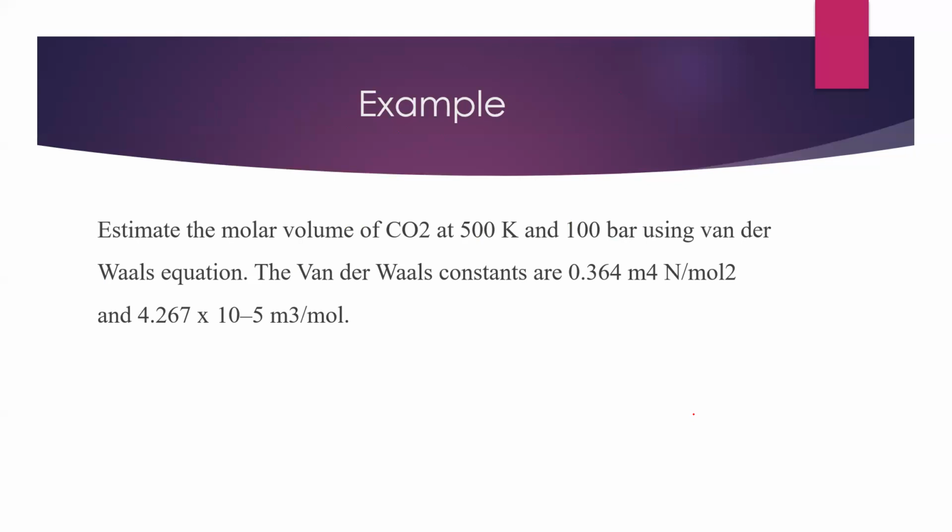So now this becomes a very complicated question along with units and everything. So first of all, take care of your units. We have to decide which unit we want pressure to be in, which unit we want volume to be in, and temperature is of course going to be in Kelvin. Then based on the units of pressure and volume, we'll decide the value of R to be taken.